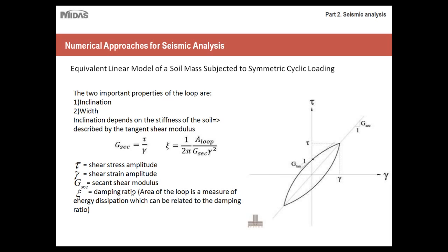The damping ratio is also dependent upon the area of the loop. I'll go into more detail about damping ratios, but just keep in mind that the damping ratio, the parameter you input for the soil under seismic loading, is directly related to a model such as this.